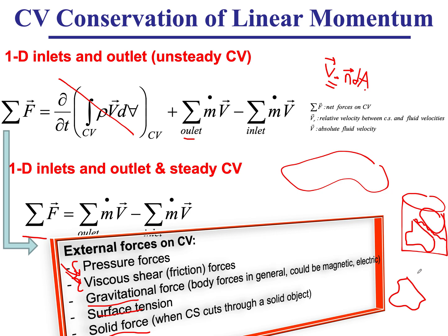is imposing a pressure force, or is exhibiting a pressure force that acts compressive and perpendicular on this particular surface. That pressure could be varying, or it could be uniform, or it could be hydrostatic, or it could be hydrodynamic. That means it doesn't vary just hydrostatically. So it could be any of those, but we need to include the effect of the fluid that we have thrown away on our control volume. And similarly, you do the same thing for the rest of your control volume.